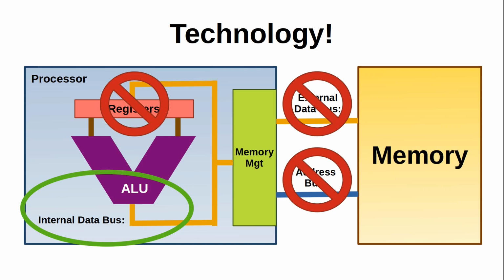So those are the processors we're going to be looking at within the 16-bit Battle Royale. Stuff that can actually do 16-bit math internally, even if it does have that external bottleneck of only 8 bits for its external data bus. And of course, the addressing can be pretty much anything at that point too. It could still just be 16-bit addressing, but most of these 16-bit processors are going to have even wider address buses, like 24 bits, even up to 32 bits, like the Motorola 68000, which we'll be seeing in later episodes.